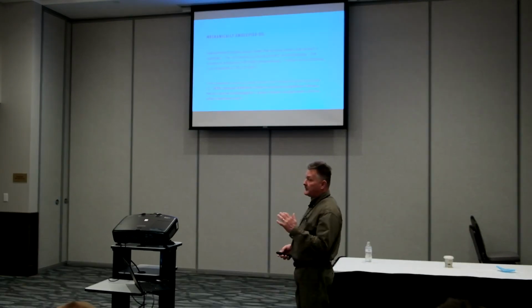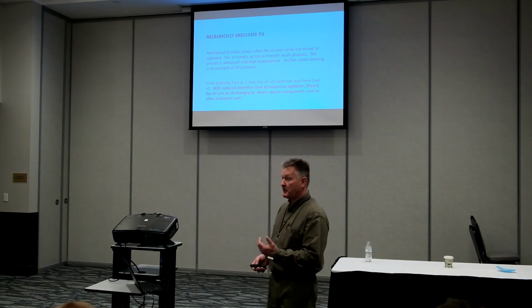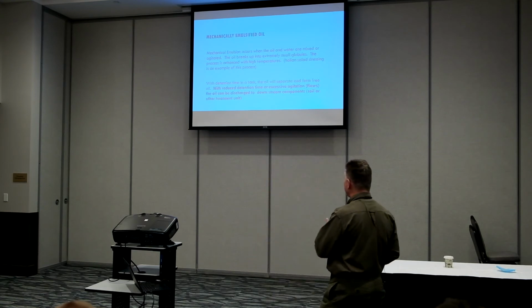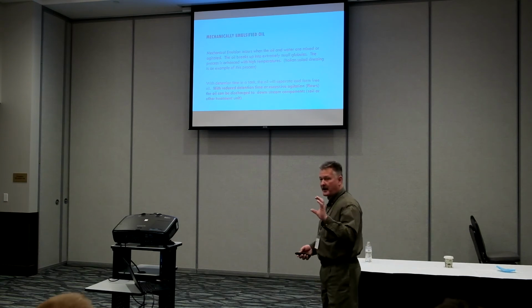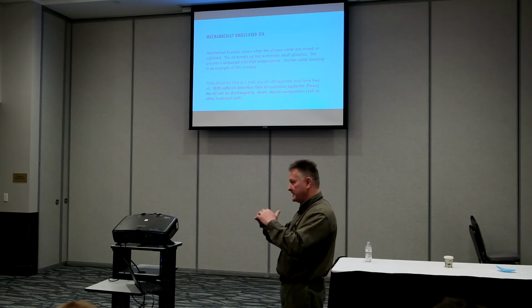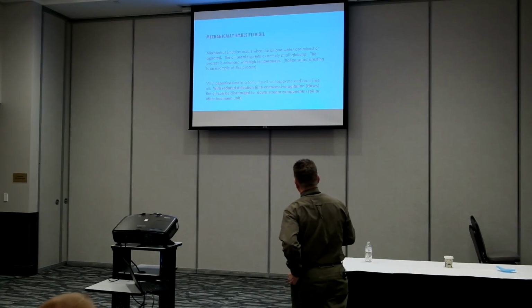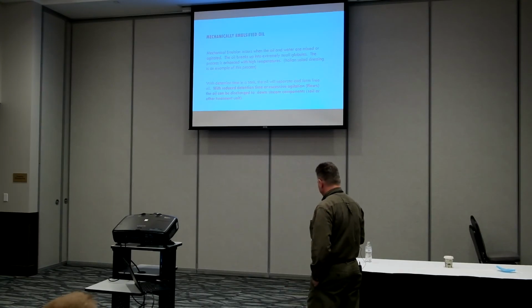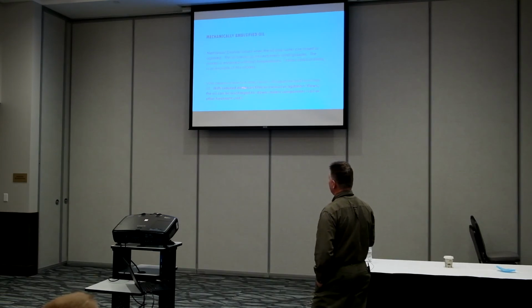But we can agitate that waste stream and create mechanical emulsification. It's kind of like taking a bottle of Italian dressing and shaking it up, and it all mixes up, and then you let it set and start seeing the separation occur. Same concept. So with detention time in a tank, the oil will separate and form free oil.